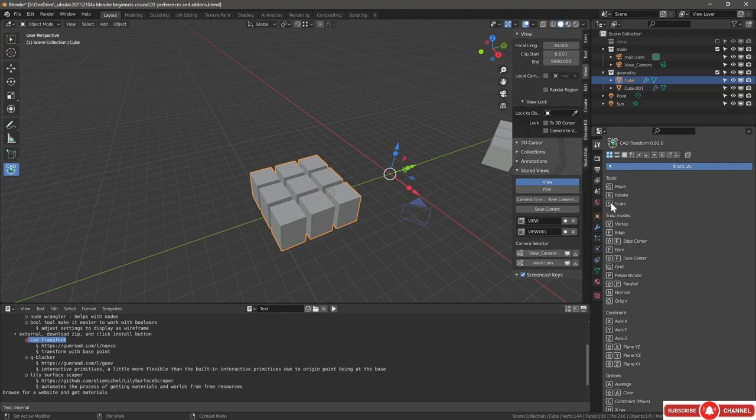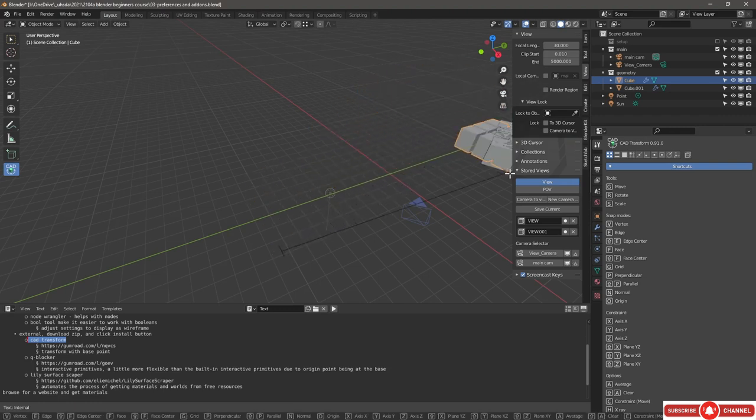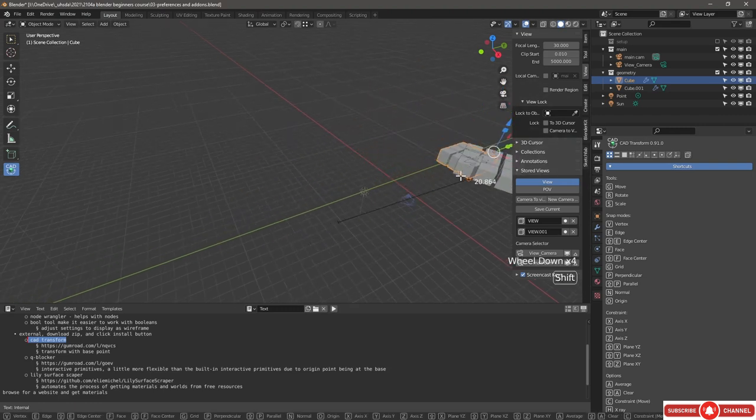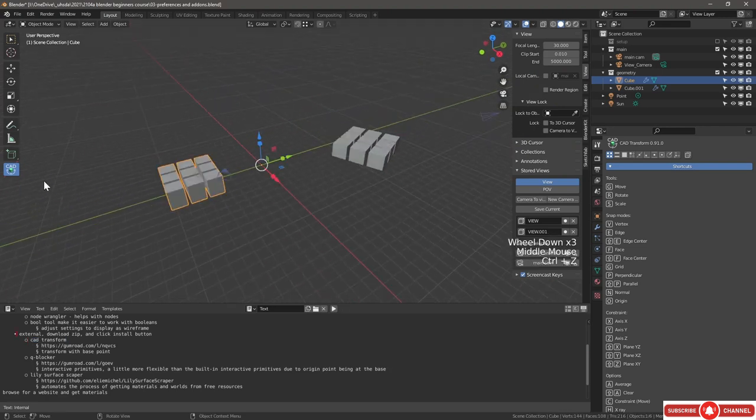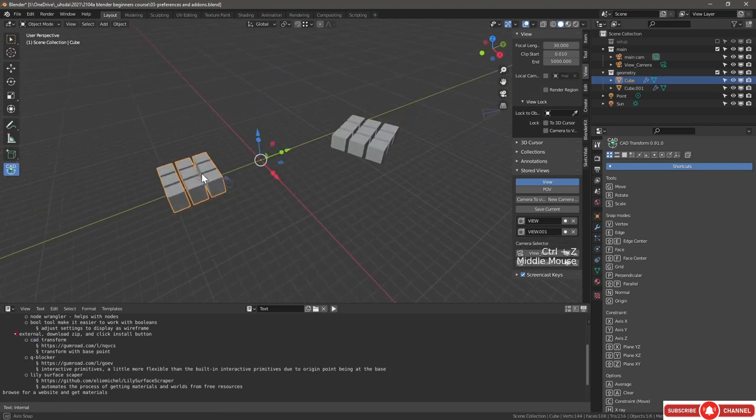Now if we click on the tool options, we get a series of hotkeys here. So G, R, and S. So G for grab or move, R for rotate, and scale. So if we press G, you can see now we can snap, and we can move much more precisely. And the important thing is we can also move in the viewport where we're snapping. That's an absolute must for architectural design.